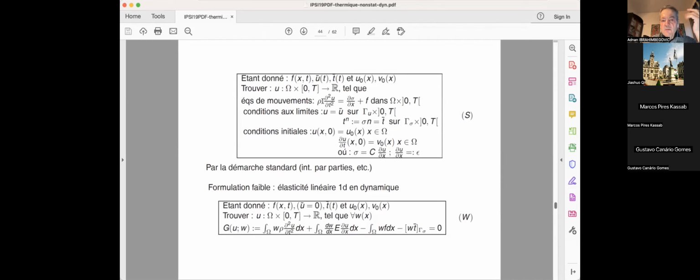So when you're describing the dynamic problem, there are additional coefficients you have to define. If you talk about a 1D problem, in statics, it's enough to define, besides geometry, the cross-section of the bar and the length. The mechanical property is just Young's modulus. Now, if you go to dynamics, you also have to define at least the density.